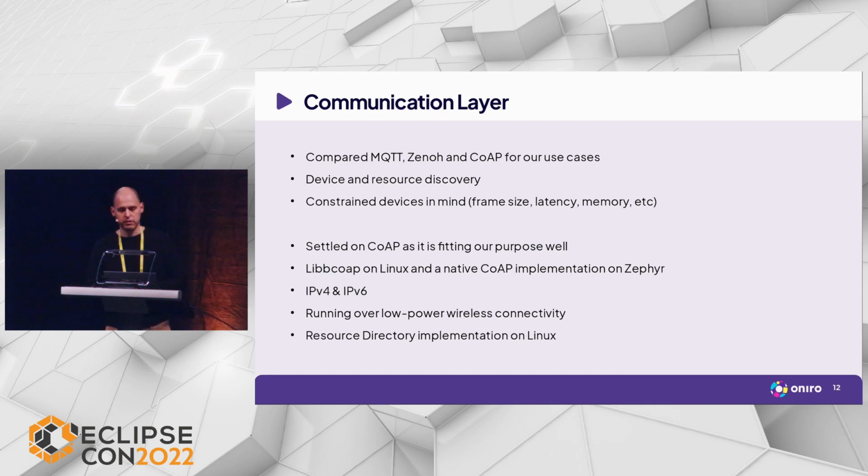And in the end, we settled for CoAP. We tested out Zenoh on Zephyr as well. We tested out MQTT on Linux as well. But in the end, we settled for CoAP. That mostly comes from the fact that we also make use of the resource directory. I'll come to that later, but that was one of the main reasons. And we have also been very happy about how it handles the low latency and frame size issues we're having.